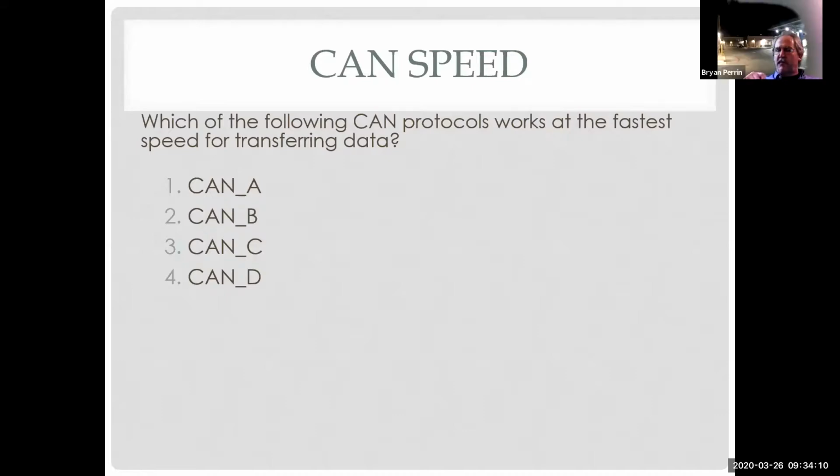As I said, for years Chrysler used two different networks, whether I was talking to their car with a generic scan tool through the generic OBD2 side, or I identified it, told it yes, I want to talk to this year, make, model Chrysler, and I have the software to do it. It went in through a completely separate network. And when I get into scan tools a little bit more, when we get into the computer control stuff, I'll expand on that a lot more.